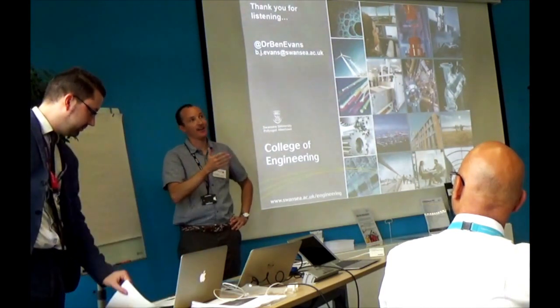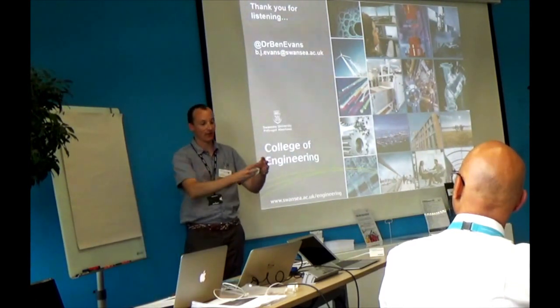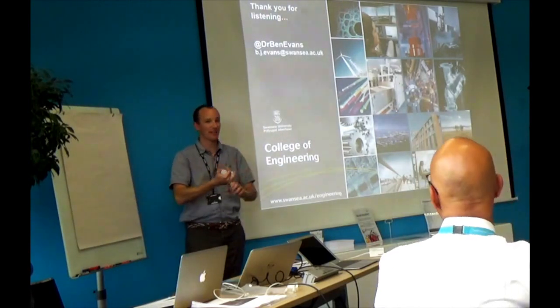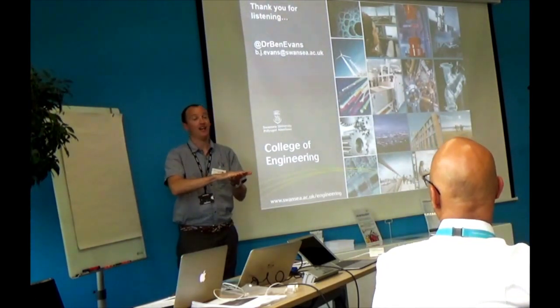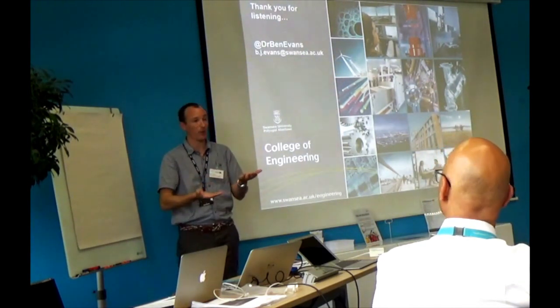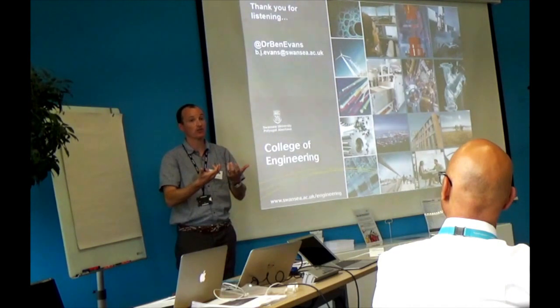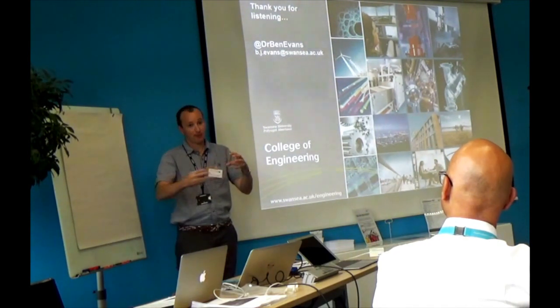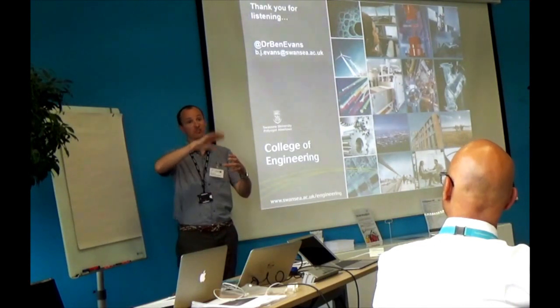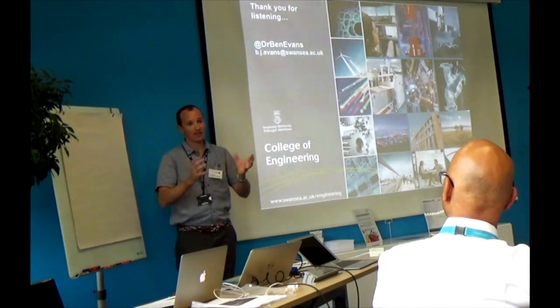And the more complicated one, which I think we will encounter when we start getting data back, is that different models will do a better or worse job at different regions across the surface of the car. Particularly underneath the car, we've got huge levels of uncertainty. What kind of surface is that? Once you start generating that bow shock, is that even a surface that can be defined in a meaningful way at all? Is the amount of particles being entrained underneath the car predictable? So it might be that different models predict what's going on underneath the car compared to over the fin, for example, where a standard RANS model with no particles does it best. That'll be a tricky thing if we find that different models are more trustworthy in different regions of the car.